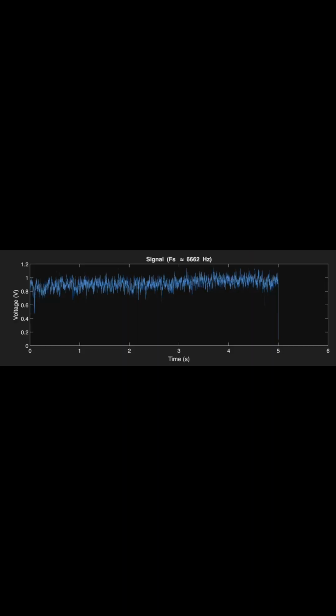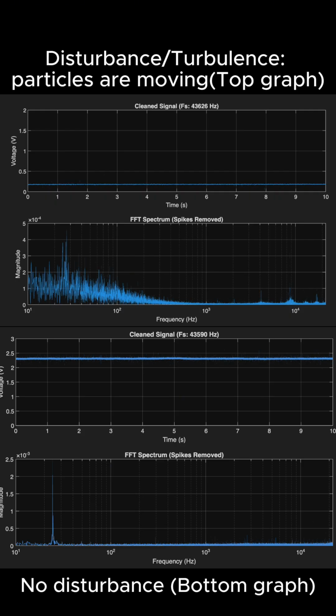We use a fast Fourier transform, FFT, in our experiment, which is used for filtering the discrete signals and obtaining a certain frequency. With many trial and errors, we finally recorded the signal with beat frequency, which is the frequency difference between two lasers. We kept seeing a peak of 30 Hz in the magnitude frequency graph, where FFT was applied when there was no disturbance in the system. This is the frequency difference between the two laser beams, which is the beat frequency.